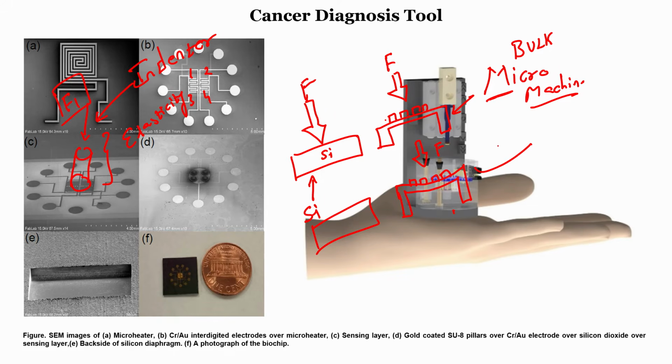This bending will cause change in the resistance, right. So, the stress in the piezoresistor will cause change in resistance. To help increase the sensitivity of the piezoresistive material, we are performing a bulk micromachining technique, by which we are etching the silicon wafer from the back side, and this is what you can see right over here, alright.